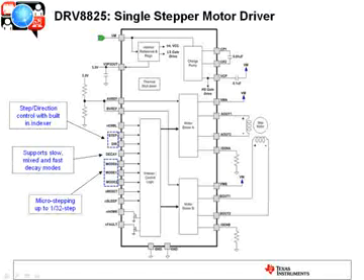In terms of the interface, this is the indexer interface. You can see here you've got the step and direction pins. Every time the step is pulsed, the stepper is going to advance or retract one position depending upon the polarity on the direction pin. You can set the decay mode. This device, when the winding current's increasing, is in slow decay mode, but when the current is decreasing, you've got a choice here. You can pick and tell it to decay in slow mode, fast mode, or a mixed mode, which mixed mode is 75%, I believe, slow decay, and then 25% in fast decay.